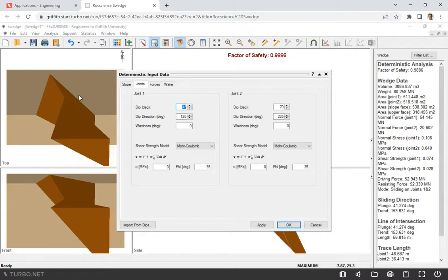So it's basically shear stress against the friction between the wedge and these joints. For both joints, when we measured, our estimation was that the friction angle was 35 degrees, so it's already preset at 35. I think it's pretty common. And cohesion was 0. If you, for example, get different values during your site investigation, you can change them, right?